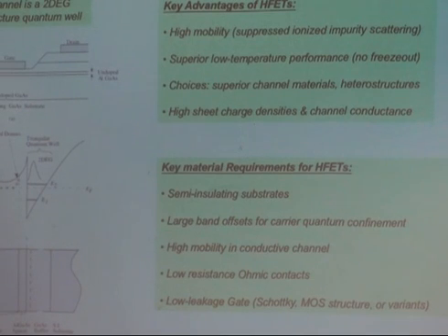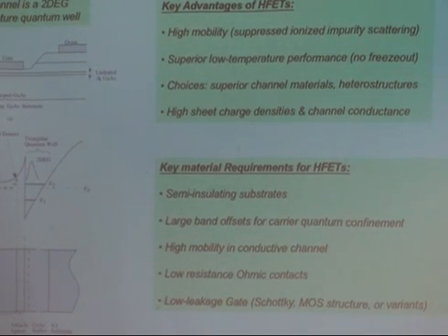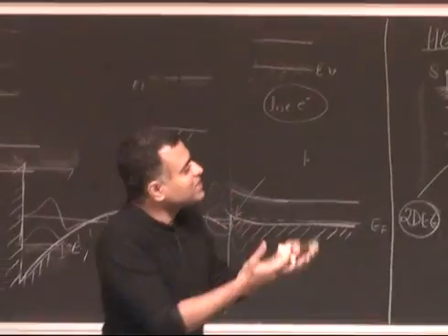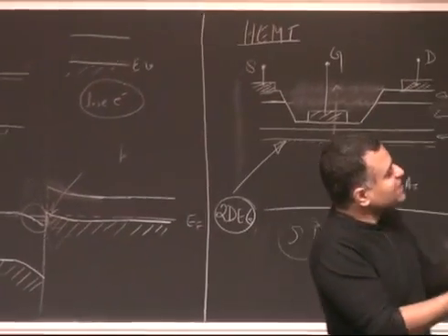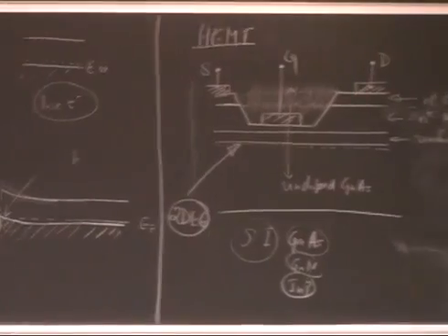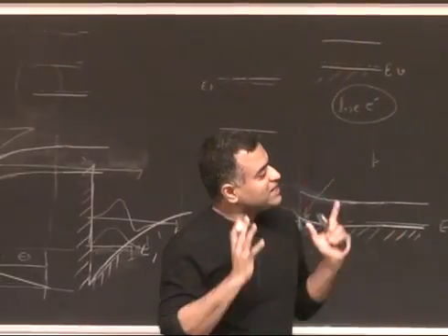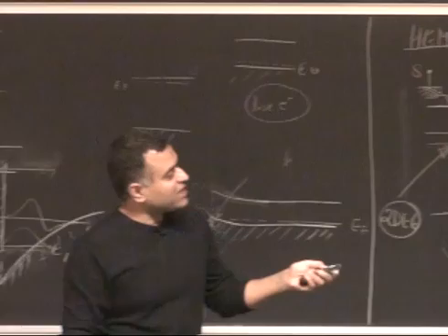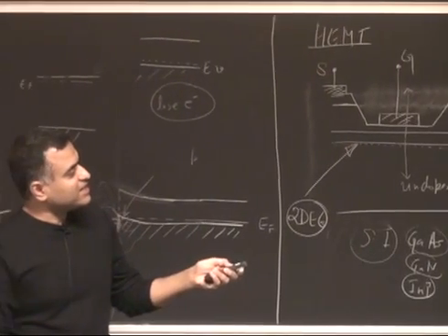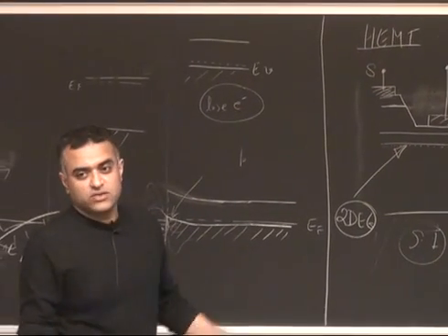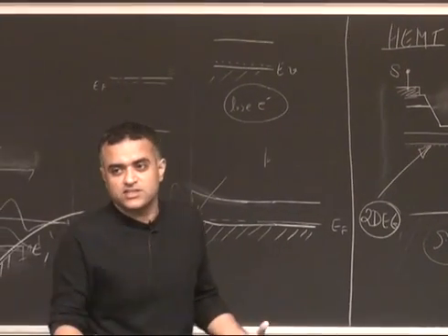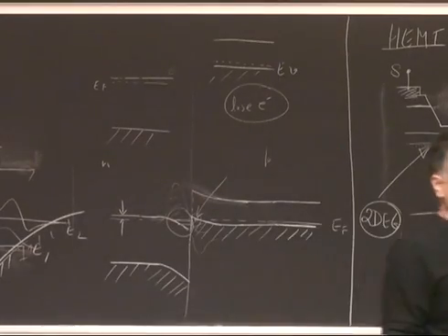If you have a conductance between the two here, then you have basically a 3-terminal resistor. There's no gain in that. It's not a transistor. Still today, you will read papers where it's clear that it's a 3-terminal resistor, but people claim it to be a transistor. But you guys know you should never say that, because the moment you have gate leakage as well as the source and drain, there is no gain in that system. It's 3 resistors. There's no gain in 3 resistors. They're all passive elements, right?